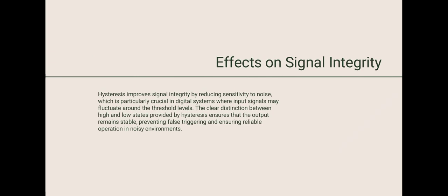Effects on signal integrity. Hysteresis improves signal integrity by reducing sensitivity to noise, which is particularly crucial in digital systems, where input signals may fluctuate around the threshold levels. This clear distinction between high and low states provided by hysteresis ensures that the output remains stable, preventing false triggering and ensuring reliable operation in noisy environments.